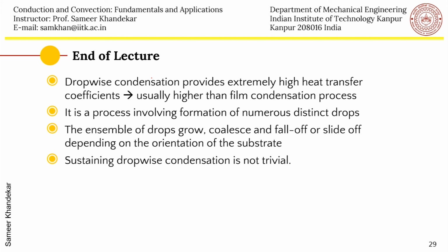So we have seen in one lecture the evolution of the nuances of the condensation process. We have analyzed laminar film condensation, with analytical expressions for the velocity profile and temperature profile, and then the heat transfer coefficient. But for wavy laminar or turbulent films, we have seen some semi-empirical and empirical correlations for film-wise condensation.